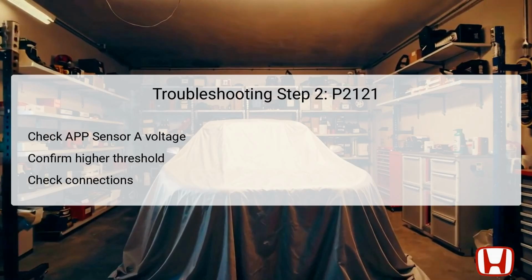In troubleshooting step 2, recheck the APP sensor A voltage using the HDS. This time, look for a voltage reading of 4.99 volts or higher. If this condition is met, it confirms that the fault is duplicated, prompting a move to step 8 for further investigation. However, if the voltage reading does not meet this threshold, it may indicate an intermittent failure. During this scenario, inspect the wiring and connections for any loose terminals or poor connections at both the APP sensor and PCM connectors. Identifying these issues may resolve the DTC without extensive repairs.